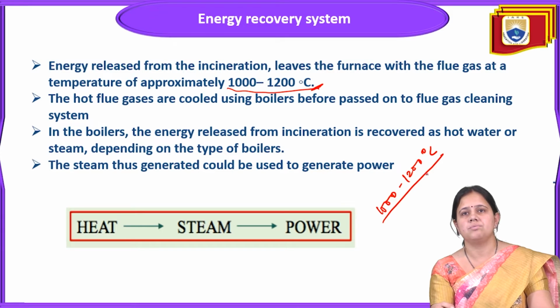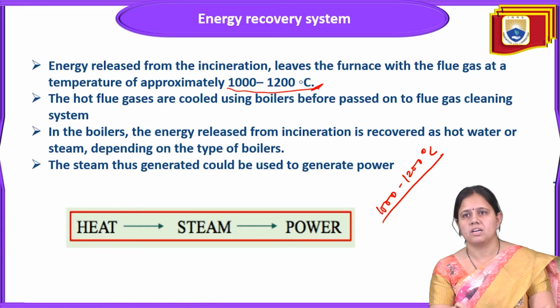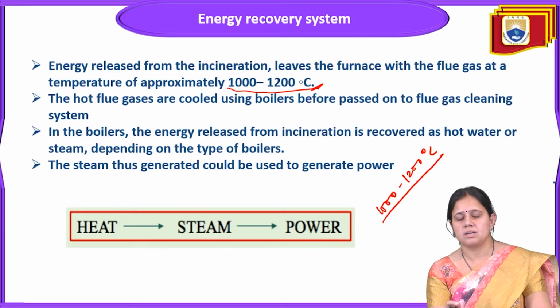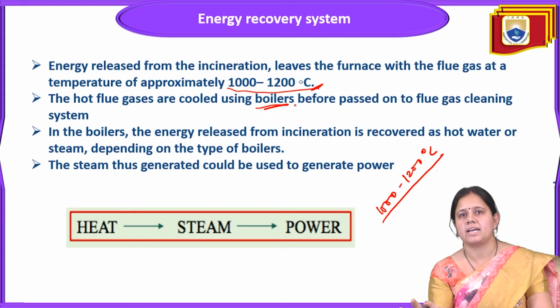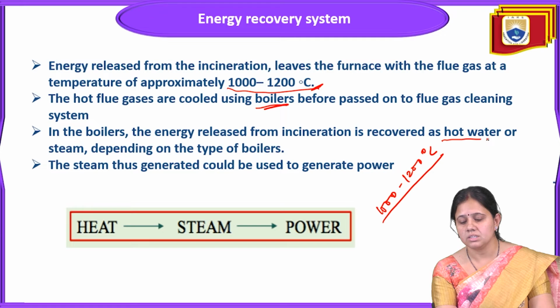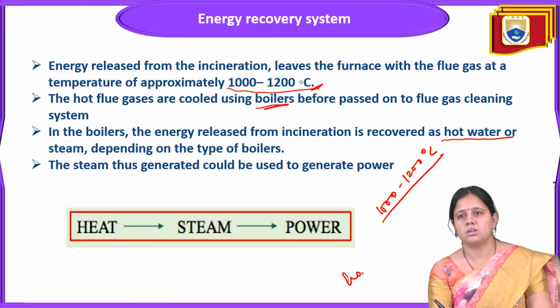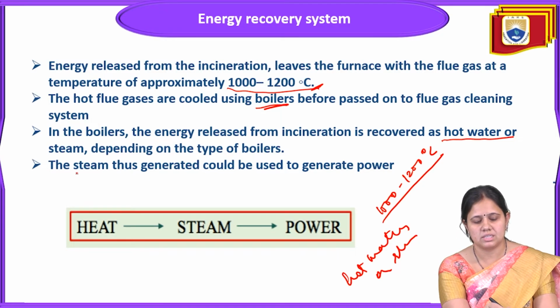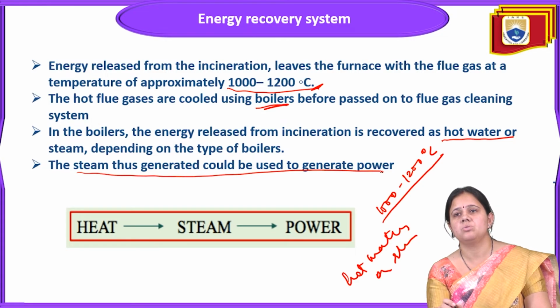Next, the hot flue gases are cooled using a boiler before being passed on to the flue gas cleaning system. In the boiler, the energy released from incineration is recovered as hot water or steam, depending upon the type of boiler. The steam thus generated can be used to generate power.